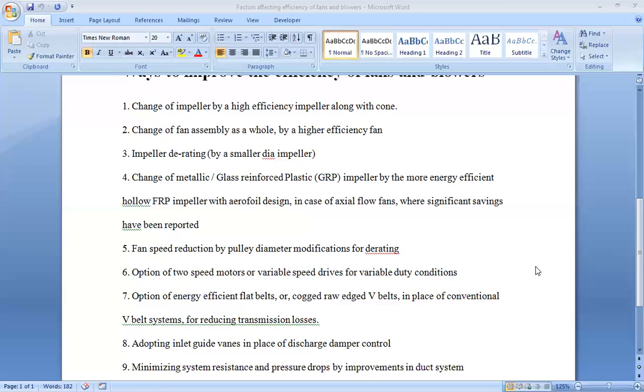We can switch off the fan for 40% of the time and switch on the fan for the rest of the 60% time, or even 50-50%. For example, the fan will be switched off for 1 minute, and for the next 1 minute the fan will be switched on, so that there will be less consumption of electricity, and our goal is also served. There is proper cooling of the transformer also.